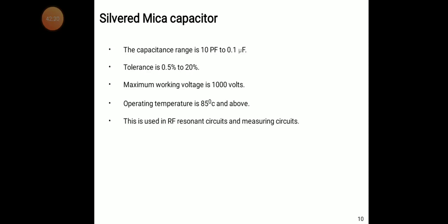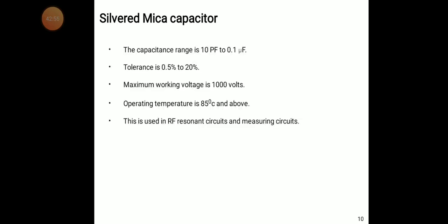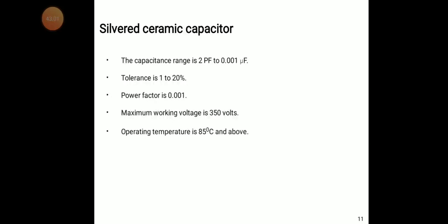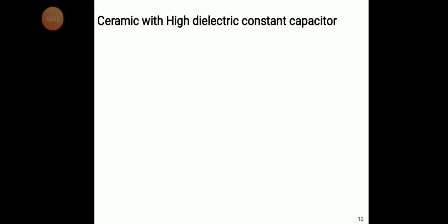Operating temperature is 85 degrees centigrade and above, same as the stacked mica capacitor. Generally this is used in radio frequency resonant circuits and measuring circuits. This is another capacitor which we generally use. So next one is the silvered ceramic capacitor.